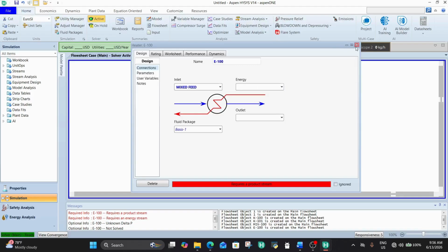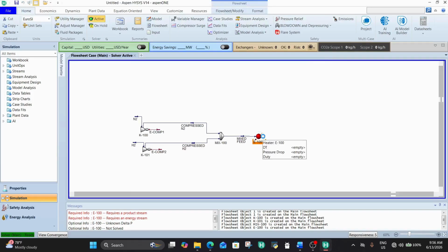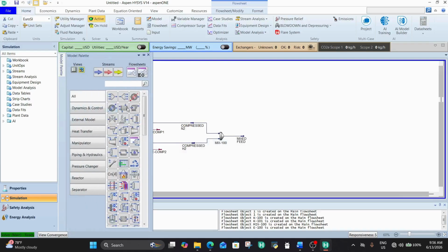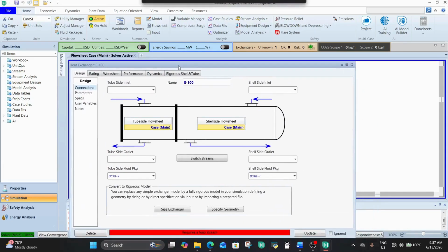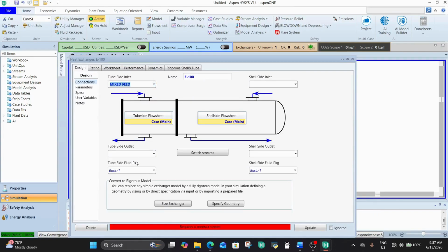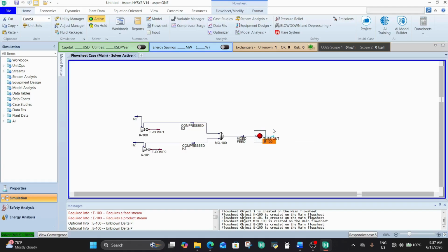So, a heat exchanger. Good. We plug our feed, let it go through the tube. Let's call this tube out. And actually, we're supposed to experience some pressure drop in our heat exchanger, around 0.1 bar to 1 bar. Let's cap the pressure drop at 1 bar.